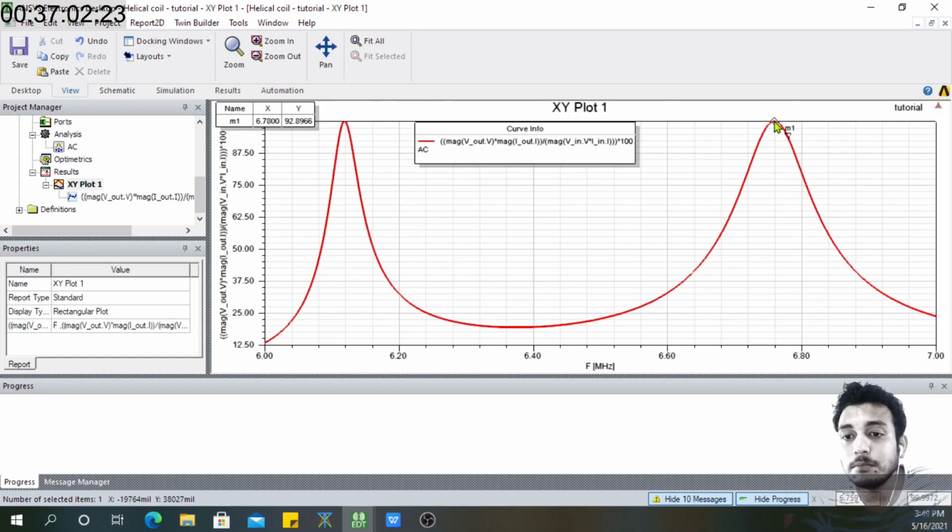If you place metal things in the periphery, there will be eddy current losses, and it depends on frequency. Particularly there will be loss inside the wire, the eddy current loss, as well as the skin effect, because of the higher frequencies. Skin effect will come into play, and obviously you can't omit that just by using standard conductors.